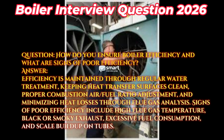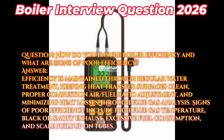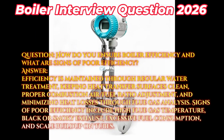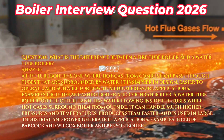Answer: efficiency is maintained through regular water treatment, keeping heat transfer surfaces clean, proper combustion air/fuel ratio adjustment, and minimizing heat losses through flue gas analysis. Signs of poor efficiency include high flue gas temperature, black or smoky exhaust, excessive fuel consumption, and scale buildup on tubes. Question: what is the difference between a fire tube boiler and a water tube boiler?